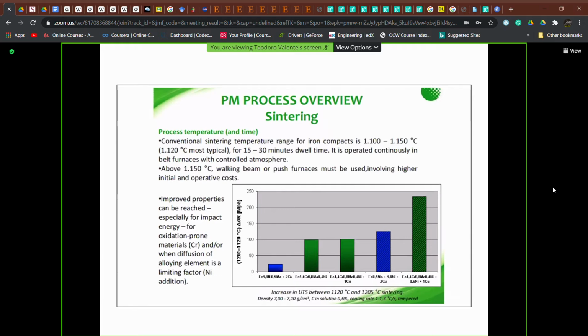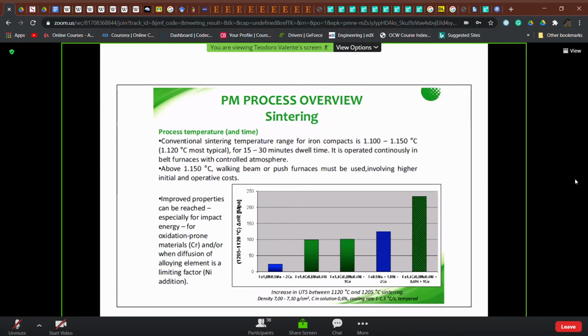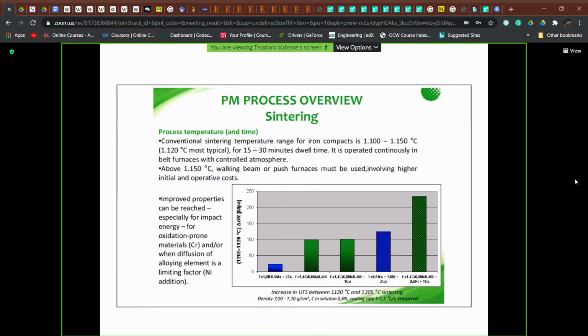So since we rely on solid state diffusion in order to recover voids, and we cannot wait years, but we are discussing production technologies, which must be compatible with engineering time for fabrication of components. Generally speaking, each kind of material has its own range of optimal temperature values.